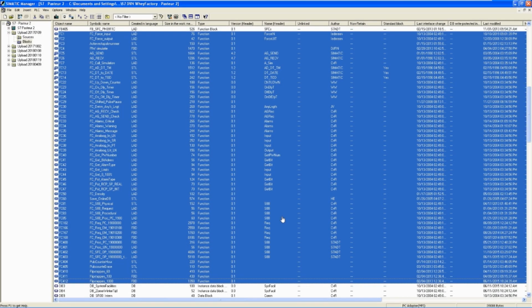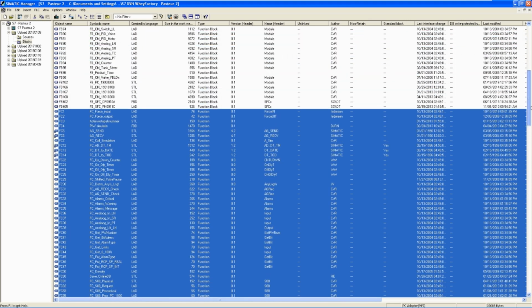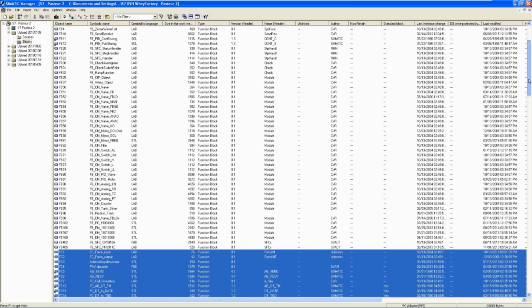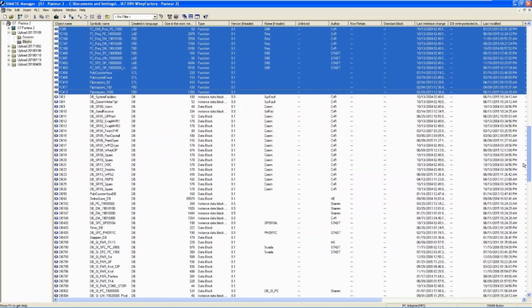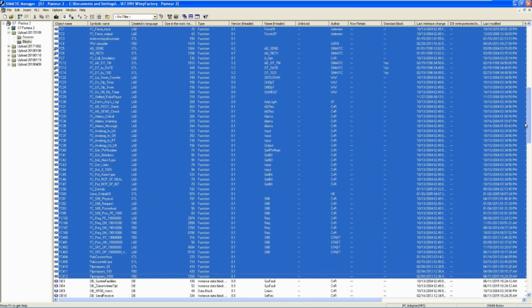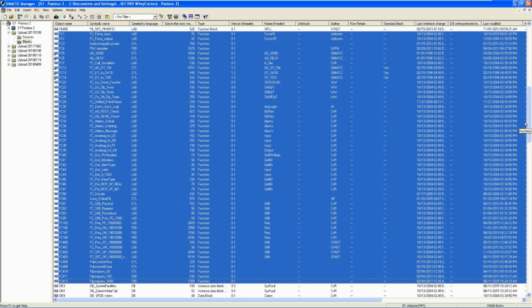The pasteurizer that was just demonstrated was replacing a conventionally built PLC application, which you see here. The conventionally built PLC application consisted of organization blocks, function blocks, functions, and instance memory. The functions are the unique part of the software.